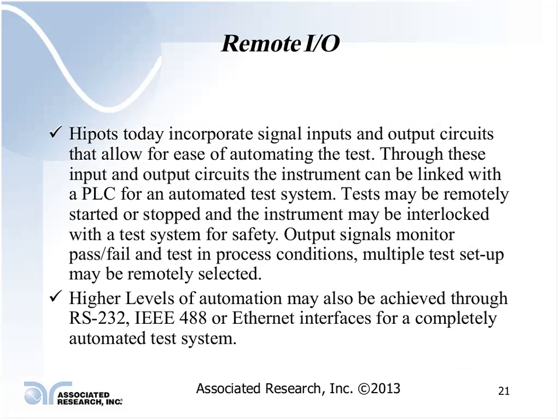Okay. Again, your instruments today have remote I/O functions. You can utilize a programmable logic controller to control the Hipot tester, sending test commands, selecting different memories, resetting the Hipot tester. Some of the old remote I/O functions: we had a 10-volt analog circuit that we used in some of our older instruments. We still offer that on some of the Hipot Ultras.